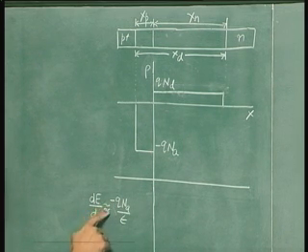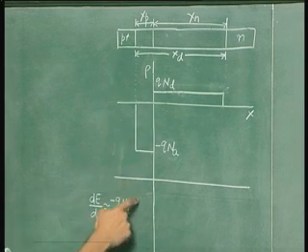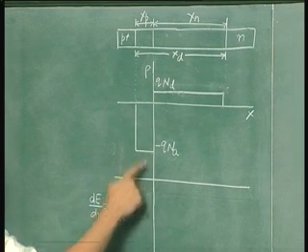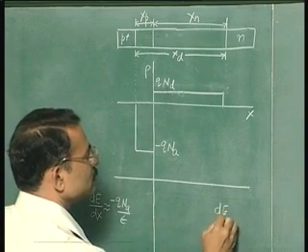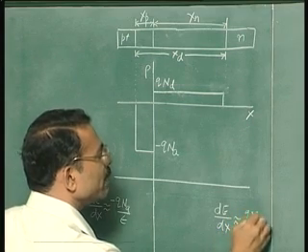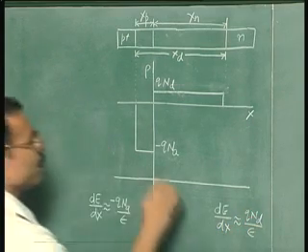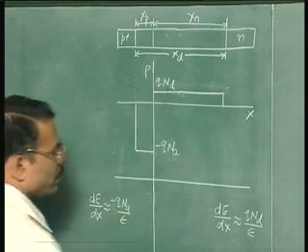So dE by dx is approximately equal to minus q Na by epsilon on the p side for this space charge, and on this side you have dE by dx approximately equal to q Nd by epsilon, that is for this picture.